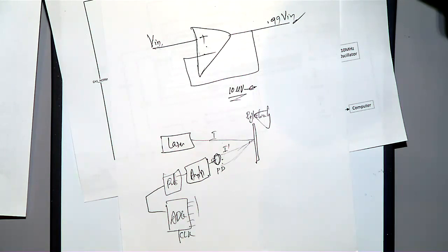After the ADC, what do you need? Okay, you are putting a digital buffer. Yeah, that's fine. Buffer, because you have to write it into the SD card. So how will you write it? How do you interface with the SD card? Can you interface by parallel with the SD card, or is it SPI? Anything you can use. Could you use some clocks on the buffer and have it go straight into the SD card without using it?